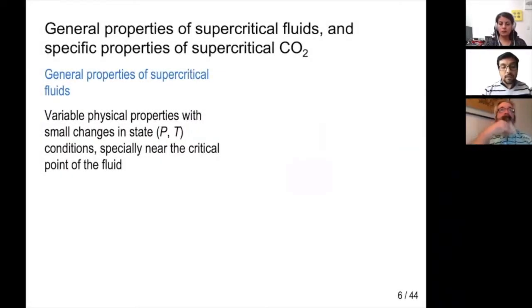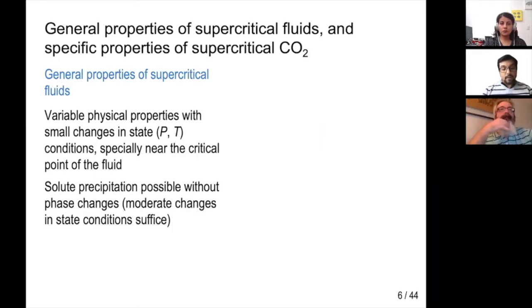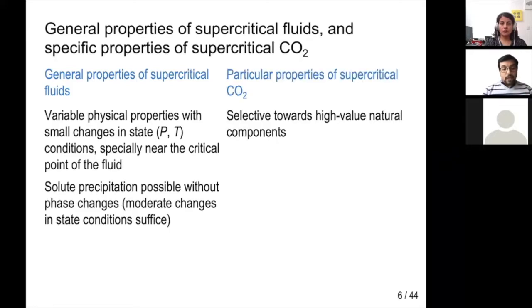Supercritical fluids have common features that make them attractive as solvents. Physical properties vary in a wide range with small variation in temperature and pressure, especially near the critical point. Solubilized solute can precipitate without phase changes. In particular, CO2 can extract high-value compounds from natural resources such as aromas.